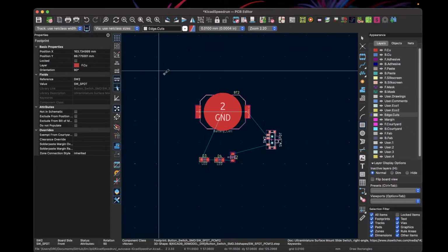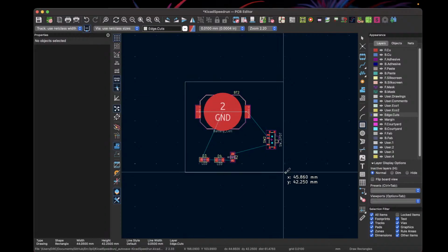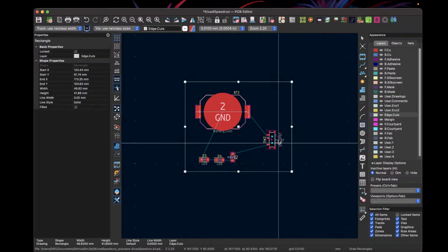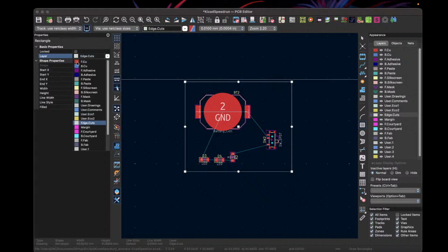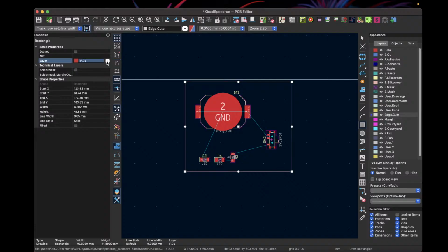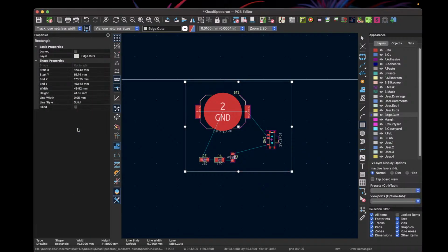But just for real quick, just to show, I clicked on this box icon over there. You could, if you wanted to, just draw a box. And this happens to be assigned to edge cuts because I had already highlighted that. You could change that around and assign it to something different. So that could be a front copper trace there. It could be something else. It could be a silkscreen outline. But we want to assign it to the edge cuts file just for this example, and that tells the fab house where they want to cut the board out. So for any PCB that you're looking at, that border where it has been cut out is because of the edge cuts file for it.